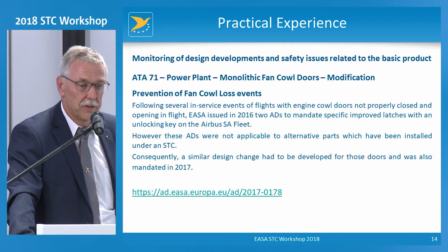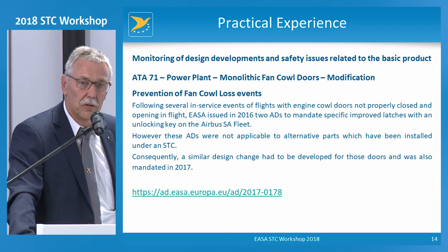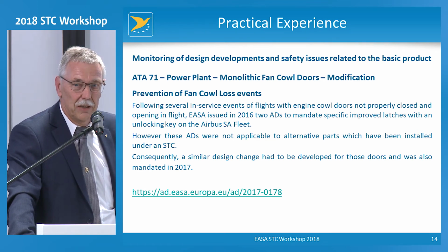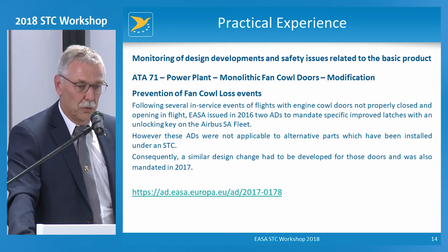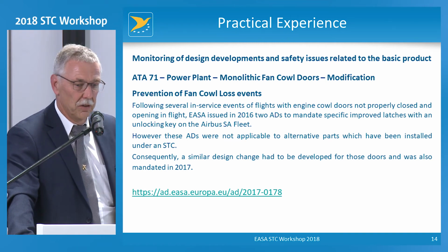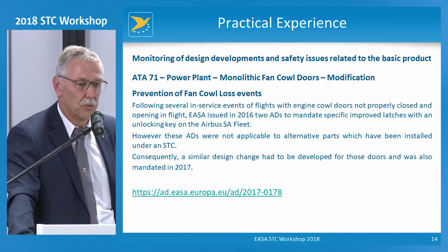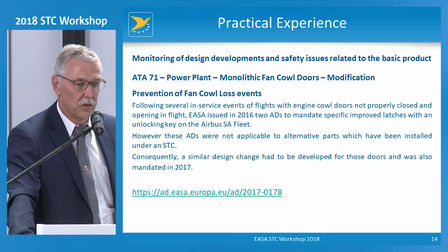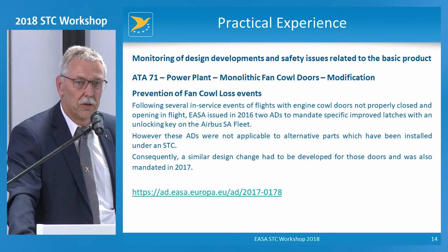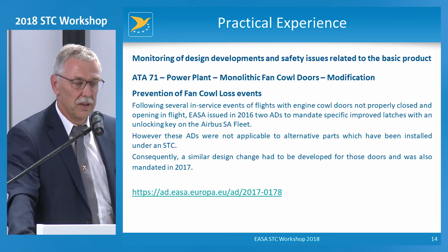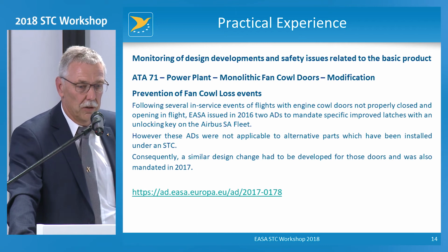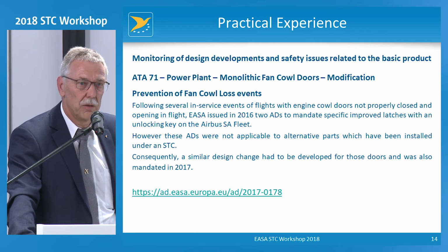But then we discovered that these fan cowl doors are also produced under STC, and therefore there was a need to develop similar protection with a certain locking mechanism and a flag to make people aware that the cowling doors are not properly closed for those aircraft as well, because the initial AD mentioned certain part numbers, and obviously the monolithic fan cowl doors had different part numbers, therefore the AD was not applicable.